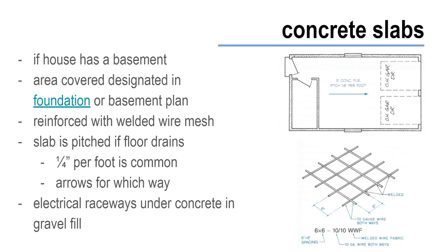Pretty straightforward idea. Your concrete floor, no matter how perfectly it's laid, no matter how many dehumidifiers you have running in there, is going to expand and contract slightly with changes in temperature. To allow for that, the joints between concrete slab and foundation should include a compressible expansion joint material.